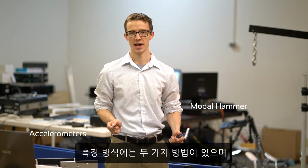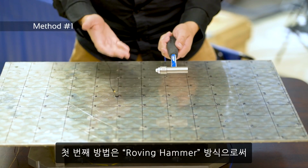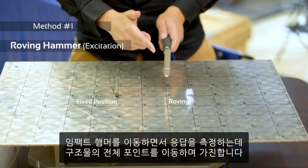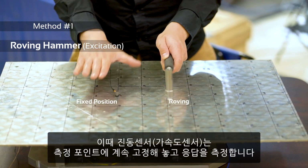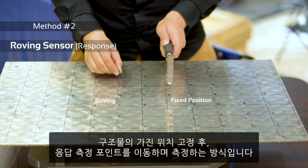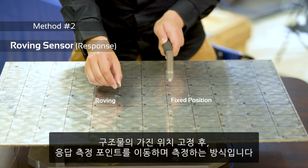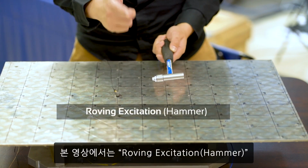There are two methods, and both methods use excitation as the reference. The first method is the roving hammer method, in which you use a modal hammer to excite the structure at various measurement points. The response points are fixed. The second method is the roving response method, in which the excitation points are now fixed, but the responses are measured at several points. For this video, I will demonstrate the roving excitation method.